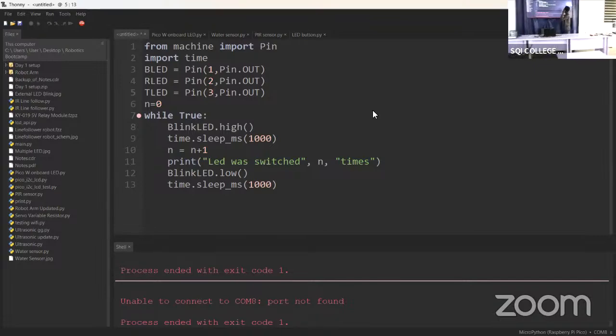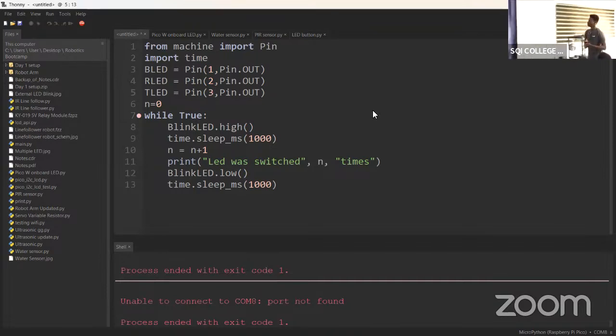Now remember, I said this delay is in milliseconds, yes? That 1000 means 1 second. So if you go lower, if you go 500, you are going to get half a second. You understand? Just like that. Has every group performed their own? Can we continue?